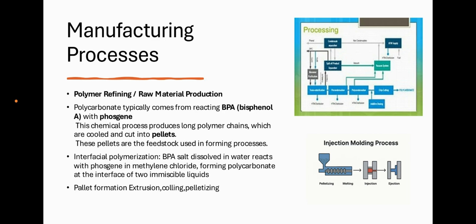Interfacial polymerization: BPA salt dissolved in water reacts with phosgene in methylene chloride, forming polycarbonate at the interface of two immiscible liquids. Pellet formation: extrusion, cooling, and pelletizing.